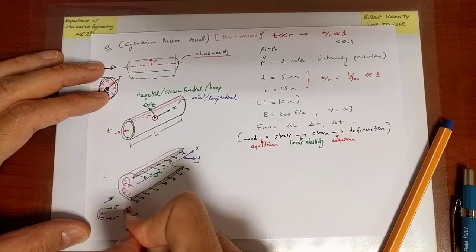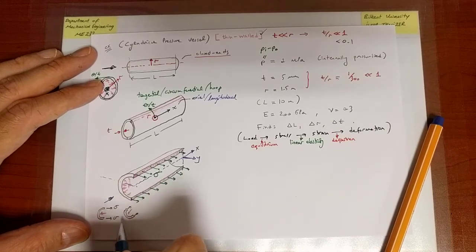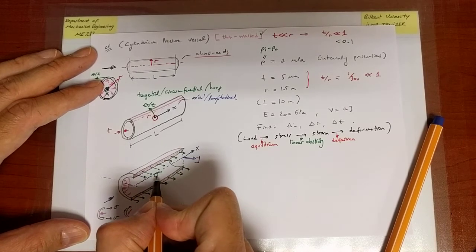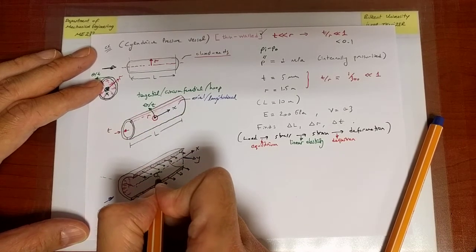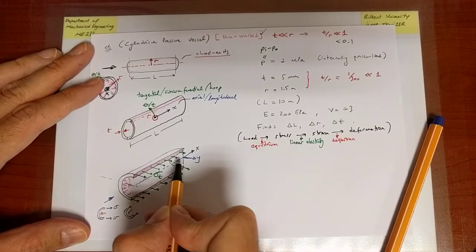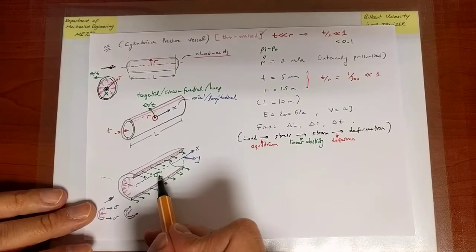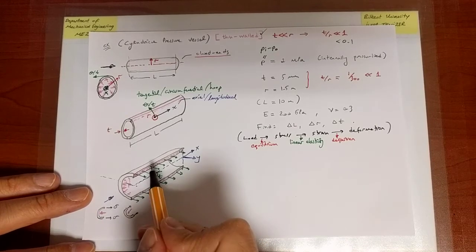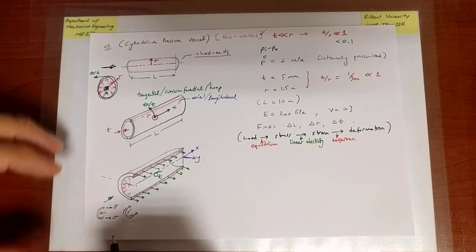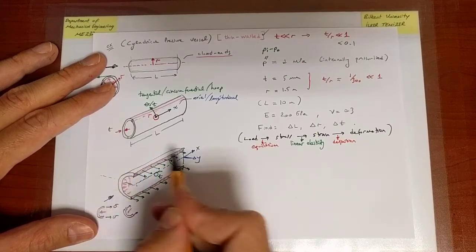And so on, every time the direction of the opposing normal stresses is along the hoop direction, the circumferential or tangential direction. The stresses that are forming, I'm going to call in general sigma t or theta. Presently I've indicated that direction to be y, but in general that would really be a tangential direction. So sigma t, a normal stress associated with the tangential or hoop direction, is forming as a result of the pressure acting on the cylinder, and those stresses will help equilibrate this free body diagram.